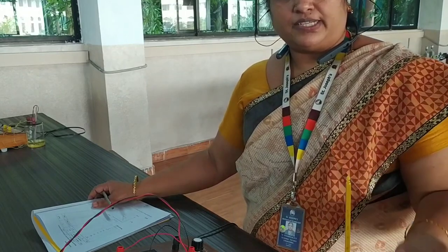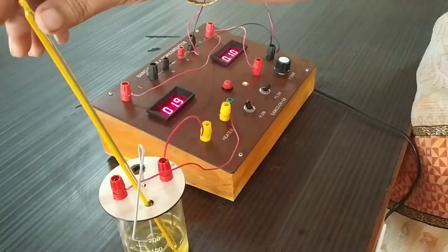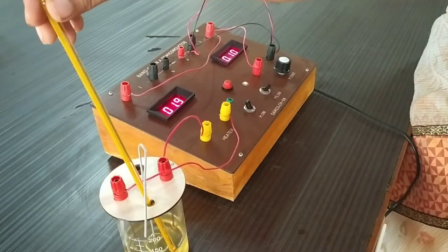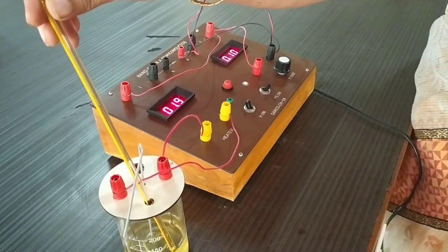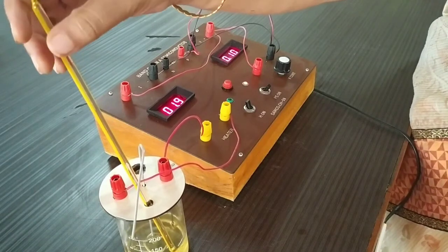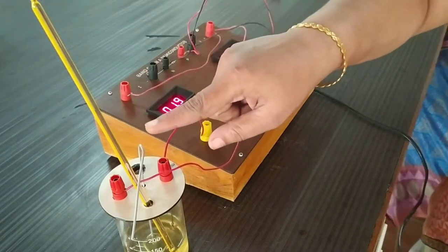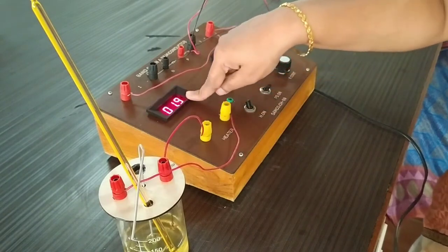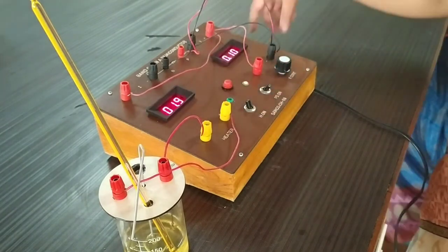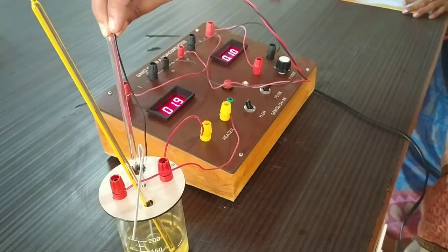You can see the temperature is slowly rising. You can see I have heated up to 80 degree. I will wait till it reaches 75, then I will start taking the readings. For each degree decrease of temperature, we are going to note down the ammeter current. Before that, I am going to put this diode inside the hot temperature bath.